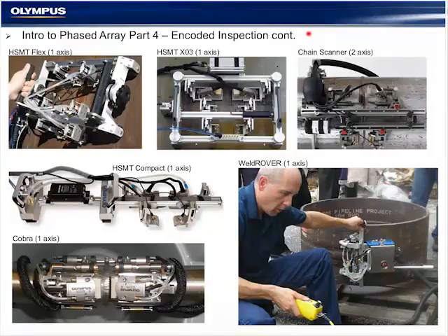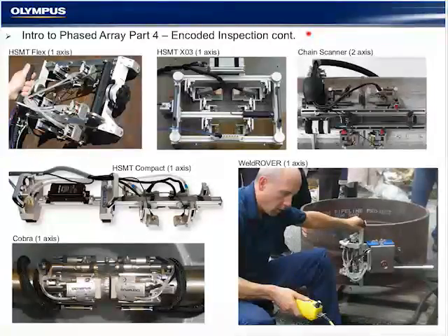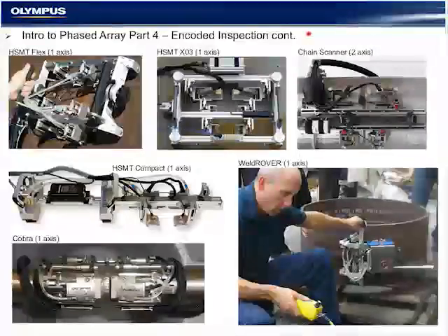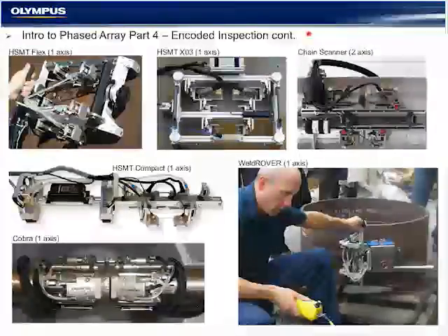The best scanners are ones that are designed for one particular application. And the more a scanner is adapted to accommodate multiple configurations to include TOFD, phased array, multi-probe, TOFD and phased array in different one-sided, two-sided access, automated, manual, the more versatile the scanner is, the more complicated it becomes.